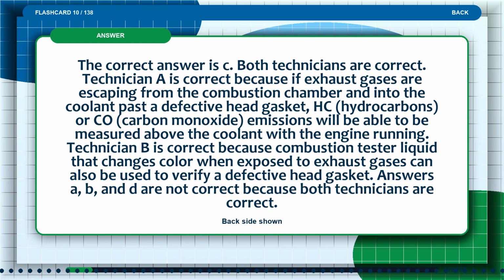The correct answer is C. Both technicians are correct. Technician A is correct because if exhaust gases are escaping from the combustion chamber and into the coolant past a defective head gasket, HC hydrocarbons or CO carbon monoxide emissions will be able to be measured above the coolant with the engine running.